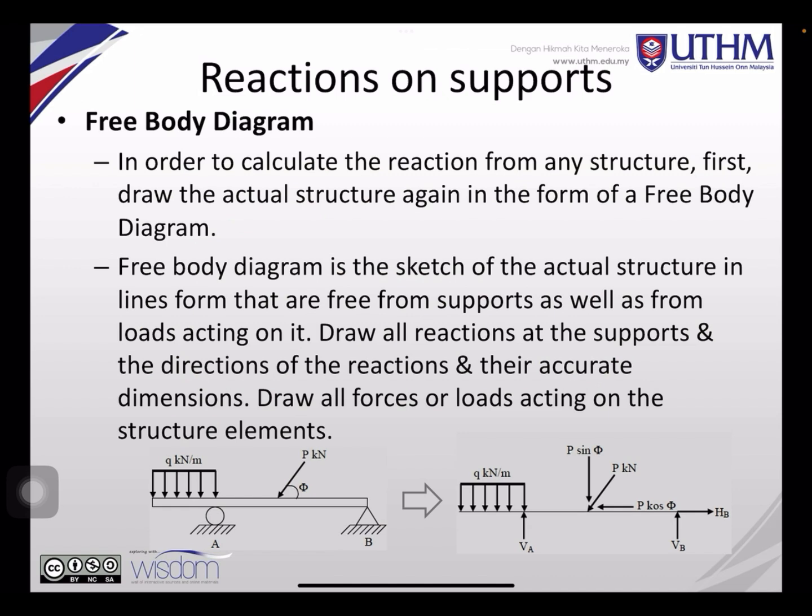Okay, so now we go to reactions on support. Free body diagram. In order to calculate the reaction of any structure, first draw the actual structure again in the form of a free body diagram. You must first have a free body diagram. You draw this, then you will have the idea on how to calculate it. So for example, this one you draw in this way.